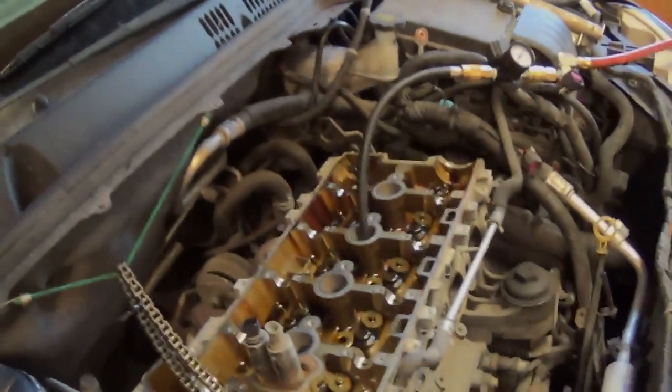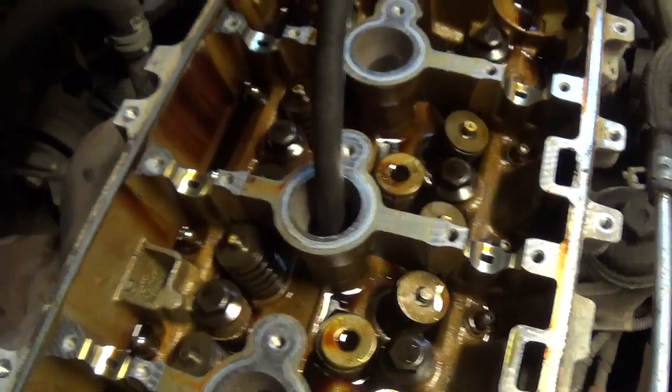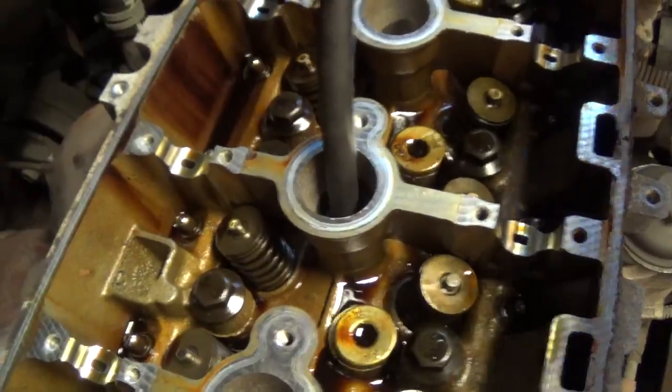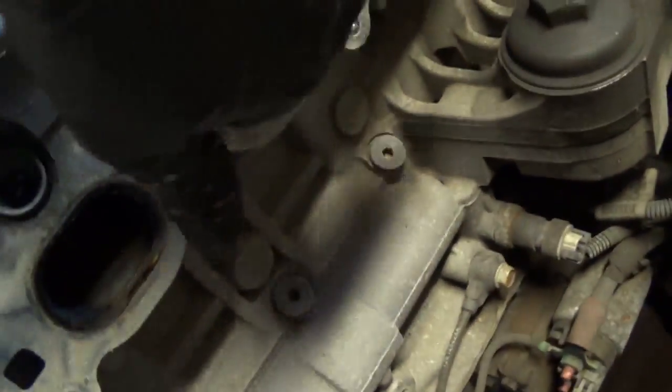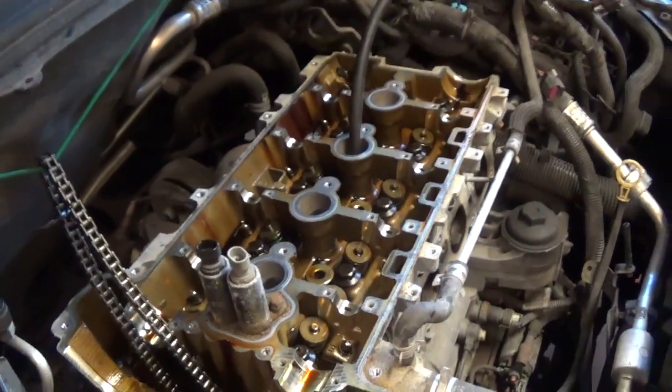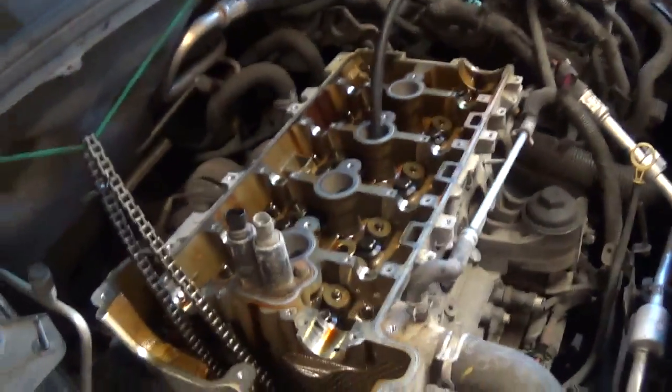Alright, just a quick confirmation of our diagnosis before we actually unbolt the head: we have our hose and pressure regulator into cylinder number 3. All the valves are obviously closed. We have no camshafts installed. Turn it up. It's coming out the exhaust ports. So that's that. Let's get this off and examine the exhaust valves.